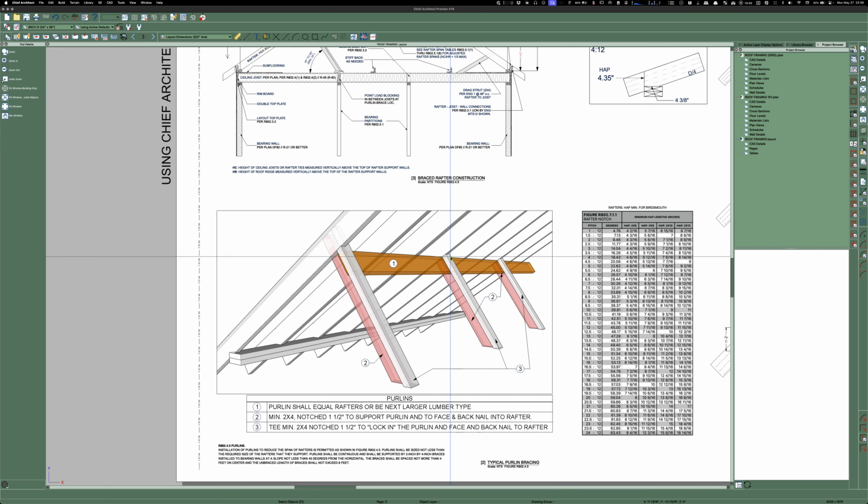Then I can take my speed square and put it on top and look down the square where the board is, right here in the face of the board, this front face, and then look down onto where there's a wall or something that is a legitimate load-bearing thing down here. And then that's where I would measure from there to the bottom of the purlin, and then up to the top of the rafter. And with those lengths, I could say, whatever this roof pitch is, that's what that angle is. And then they would cut down here 1.5 inches, and they'd rip it all the way through, and then they'd cut it off. So I would get these thrown up to me, this bottom pinkish one.